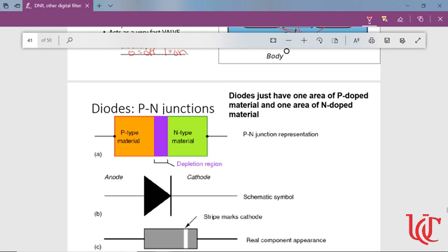So, for example, if I apply 5 volts here compared to 0 volts here, again, in my depletion region, what sign did I say would build up on the P-type material in the depletion zone? Negative. Over here, that means I'm left with positive. So if this is positive 5 volts, it'll overcome that negative charge. Or if this one was negative compared to that, it overcomes this. And now I get current to flow through it. But it's just based on what charge is applied to the ends, my N-type and my P-type material.